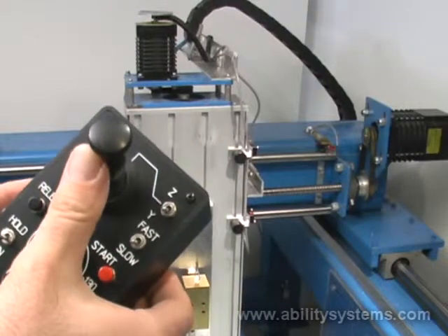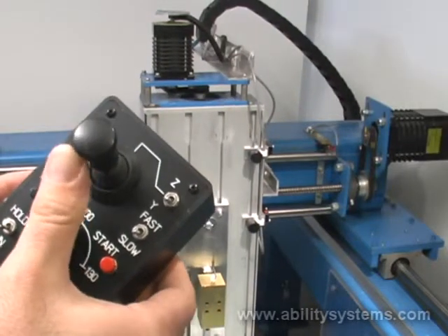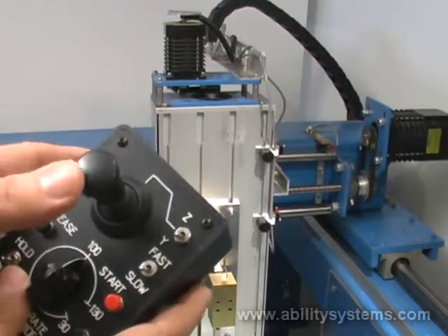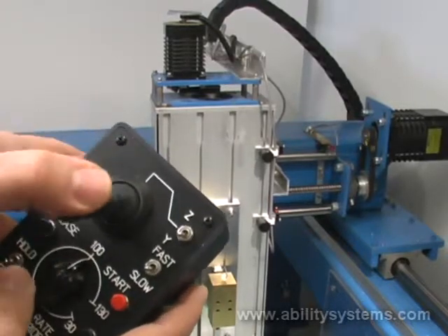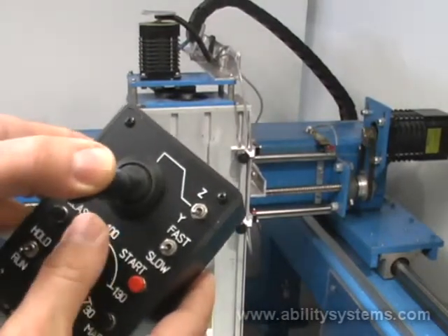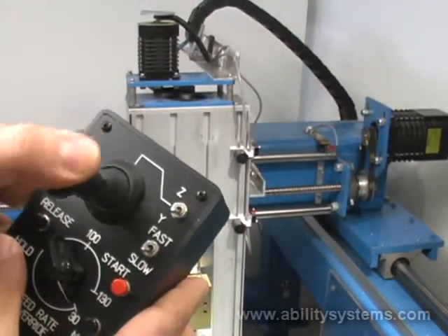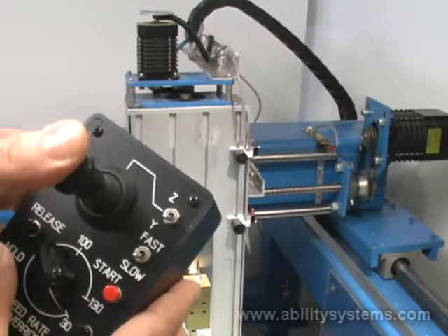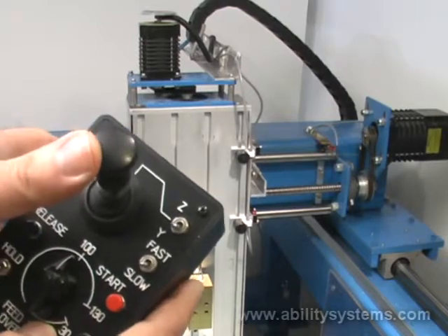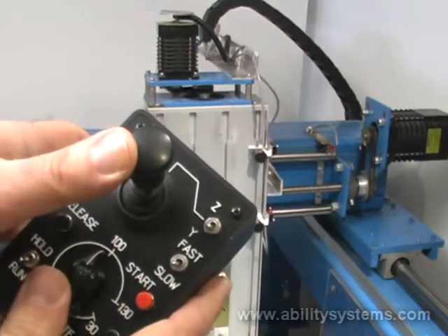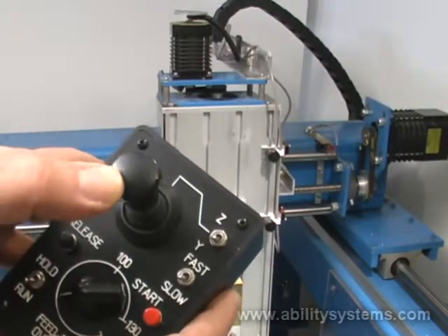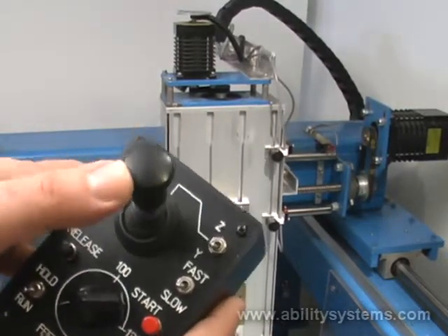The slow option, however, uses instantaneous rate, so that the motor stops the instant the joystick switch is released. The operator can still vary the instantaneous rate with the feed rate override dial, as shown here. The robust joystick response of instantaneously starting and stopping greatly increases ease of use. A separate session will be devoted to Indexer LPT's joystick option, as well as the feed rate override feature.